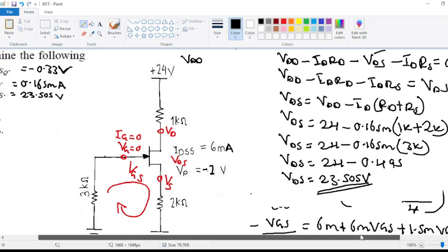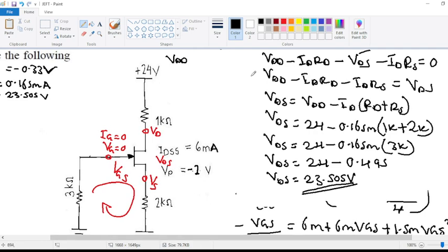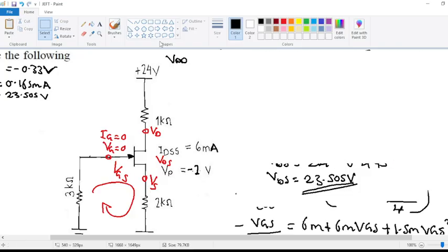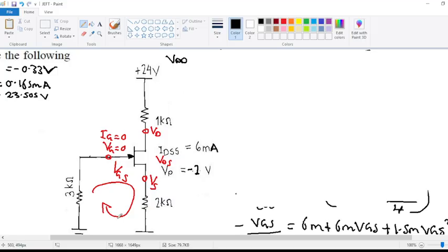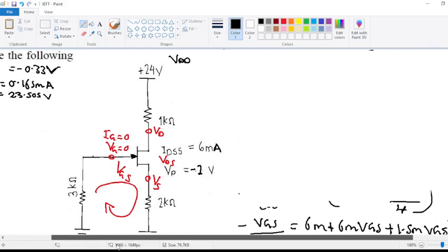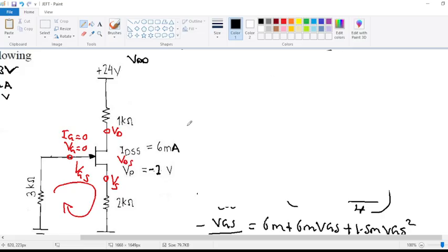We go to the VS. How do you calculate the VS? Okay, allow me to erase this part here so that we can use it, because all the formulas are going to be coming from the circuit. Our VS, okay, so our VS is what they want us to calculate, the voltage at this point here. So our VS is equal to VGS plus VG.